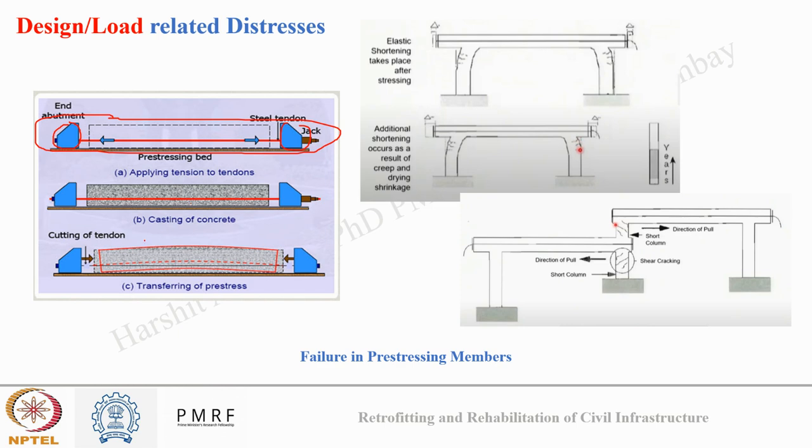Now, when the tendons are freed from the side, what will happen? The steel rebar will bend a little because they were initially provided excessive tension. So, as the tension is released, the rebar relaxes. Now, as the rebar compresses, if the concrete is weak and not properly designed, it can show some forms of map cracking. So, here you can see when the rebar regains its original length, there is a little compression in the concrete also. And if it is weak and not properly designed, it can show some form of cracking near the joint due to excessive shear stress.